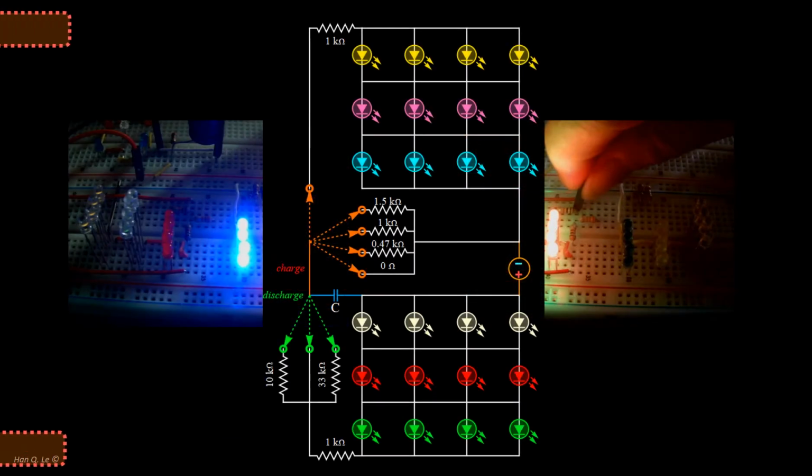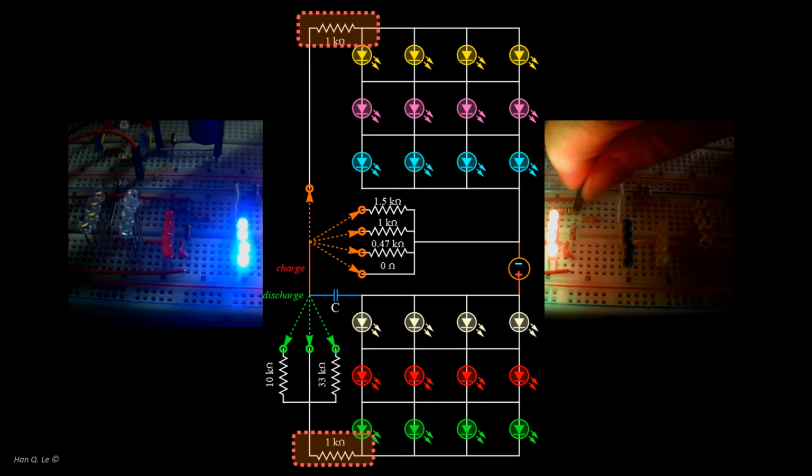The resistance is like the inverse of the size of the highway. Low resistance allows high charge flow rate and the capacitor can be filled up or drained fast. But how long it takes for a capacitor to be fully charged or discharged also depends on its size. Given a finite flow rate, the larger the capacitance, the longer it takes to fill up or drain out.